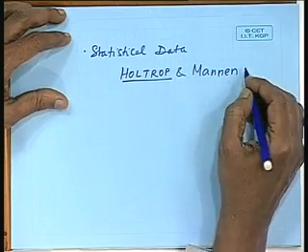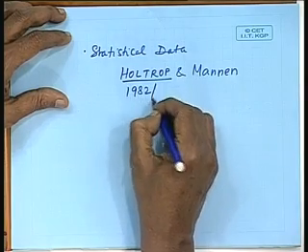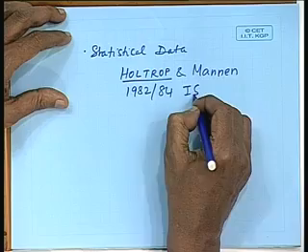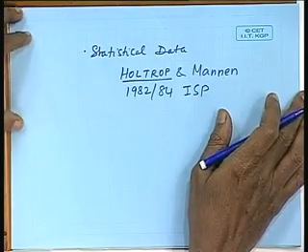They have published their statistical data analysis in 1982 and 1984 in ISP, International Shipbuilding Progress. What they give you is they have analyzed slow form ships, fast form ships, bulbous bows, non-bulbous bows, cruiser sterns, transom stern, stern immersion, various draft conditions with appendages and without appendages.